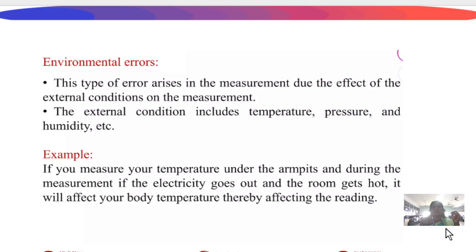For example, if we measure voltage 5 times and get slightly different values each time, that variation is due to random error. We cannot eliminate random errors completely, but we can reduce the effect of error by taking repeated readings and using statistical analysis.